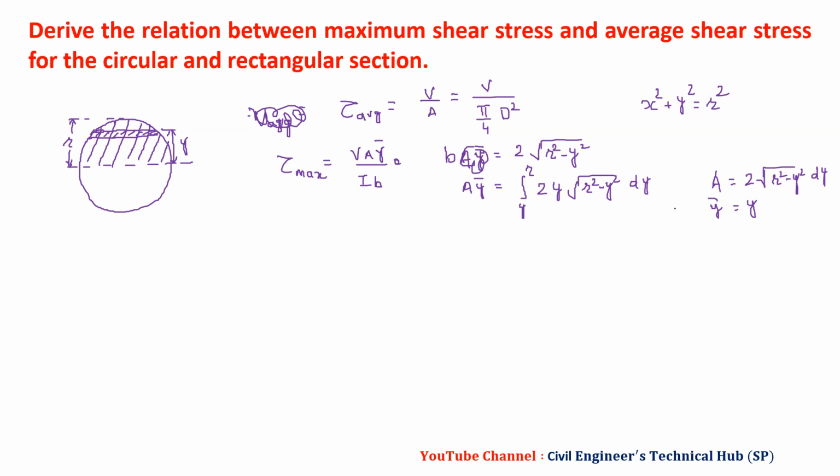So we will integrate it and put values, then we will get tau max, that is equal to, I will directly write the value, 4s divided by 3 pi r square into bracket r square minus y square. This is the value of tau.